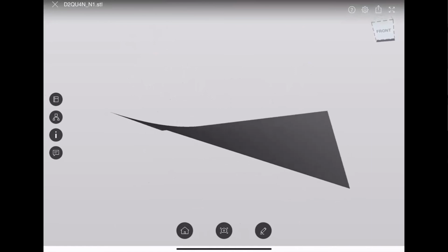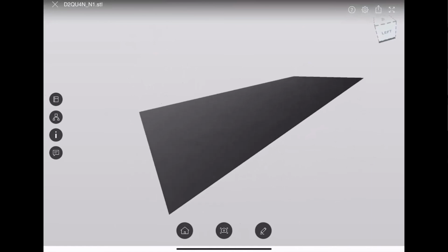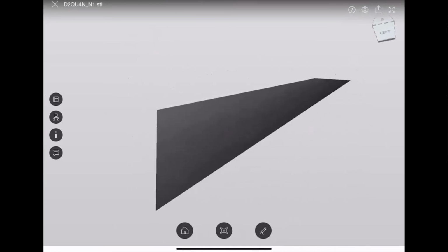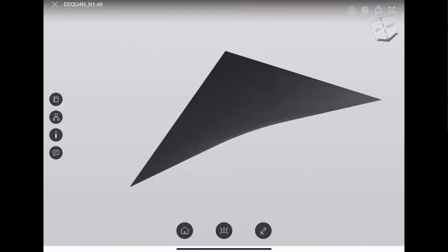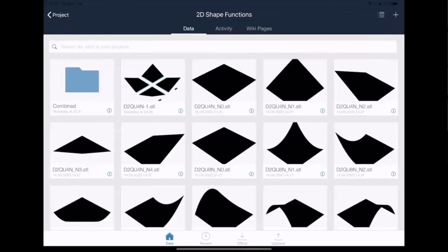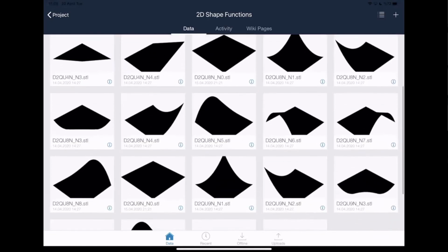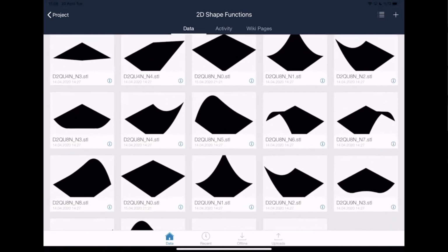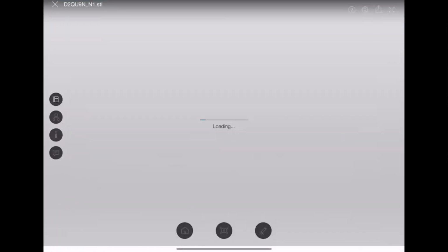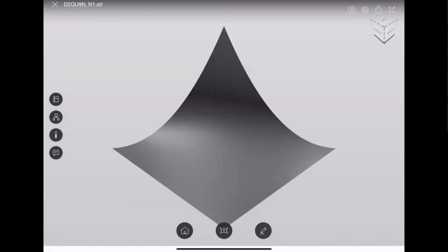I don't know if you can appreciate it, but you see how it is, right? So at the other corner nodes, it is 0. And at that node, at node 1, it's basically 1. You will see more of them, and they make sense. So for this function, it's 1, 2, 3, 4. They are similar in that sense. If you think of, let's say, the quadratic quadrilateral one, so the 9-noded one, maybe that's a better example to show to you how they look.